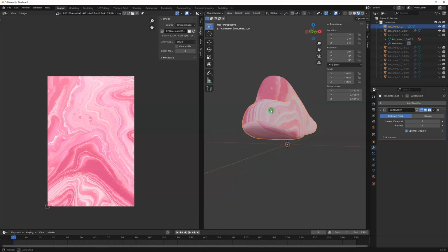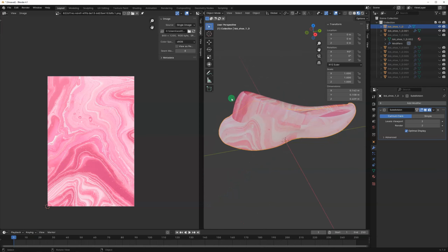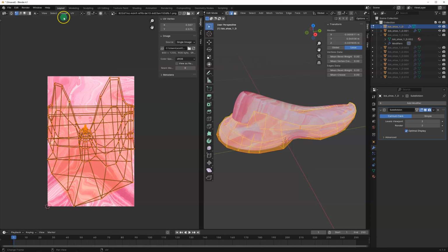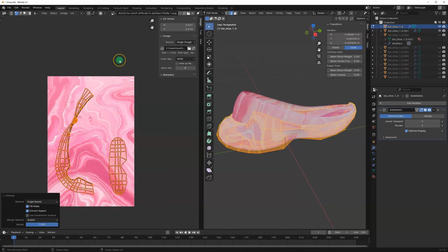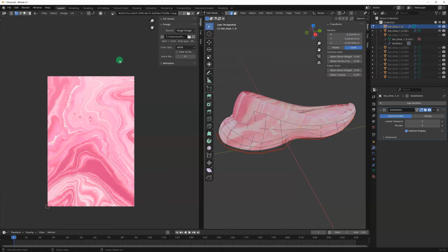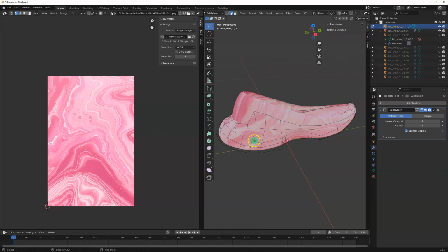But then we've got this UV seam here. But there's a whole sort of range of ways in which you can unwrap it. You didn't even have to put seams in. If we go Control Z, and then in here just go UV, unwrap. Oh no, it's still got the seams. Control Z. Let's go Alt click and then unmark the seam, clear the seam.